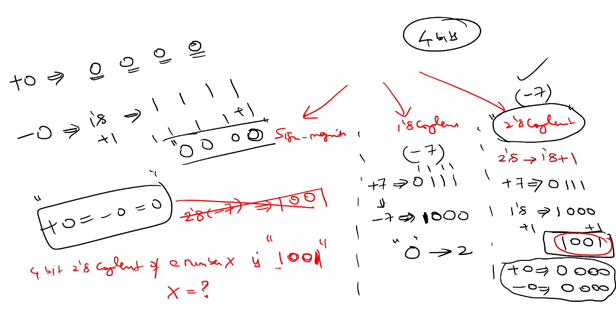You look at this number, the MSB, the most significant bit. It is 1, which means I am sure this is a negative number. Since it is negative, they would have done the 2's complement, so you have to do reverse engineering. You again do the 2's complement of 1001: 0 1 1 0 plus 1 gives 0 1 1 1. This is the magnitude.